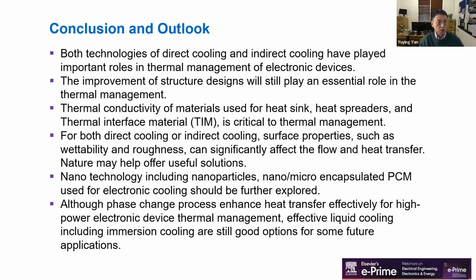Nanotechnology, including nanoparticles and nano/micro-encapsulated PCM used for electronic cooling, should be further explored. Although the phase change process enhances heat transfer effectively for high power electronic device thermal management, effective liquid cooling, including immersion cooling and liquid direct cooling, is still a good option for many future applications.